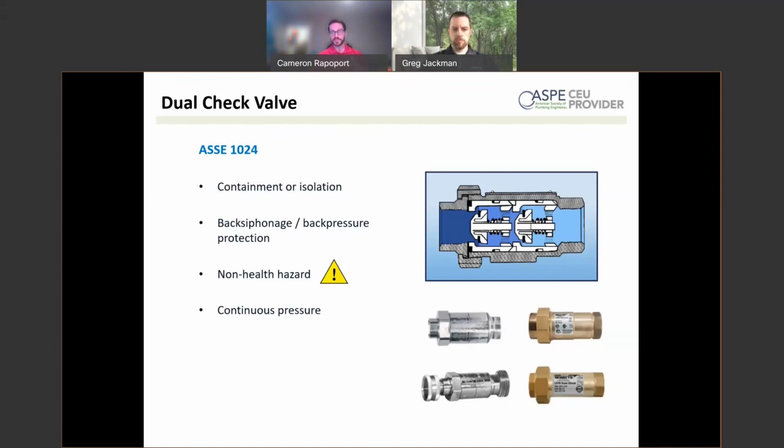They might want a testable backflow preventer. They might want a double check valve, but they might not require one at all. If you have something like a passive purge, in these residential systems you'll sometimes just run it to a toilet or something like that, where you're going to get some flow through the system. And as long as all the components are certified for potable water use, they might not even require a backflow preventer. But I wanted to bring up those dual check valves because we're seeing them more.